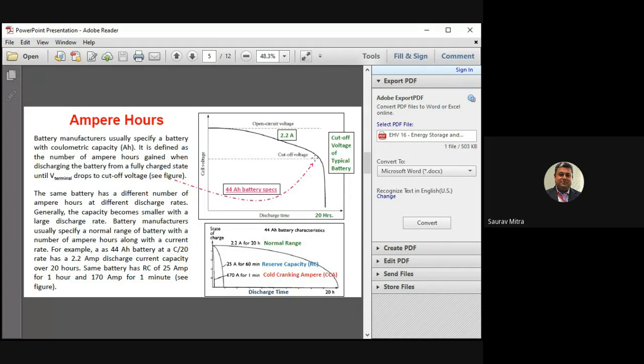And you should never take the battery to 100% charging also. That is also bad. So the best range is you should charge your battery between 30% to 80%, or best it will be 40 to 60%. When it is 40%, you connect it for charging, and whenever it is 60%, you disconnect it. But in that case, you have to charge or discharge the battery quite frequently. We don't have time for that. So that's why we charge it to 100% and we discharge it to 0%. And this actually reduces the lifetime of the battery. Exactly the same thing is happening here.